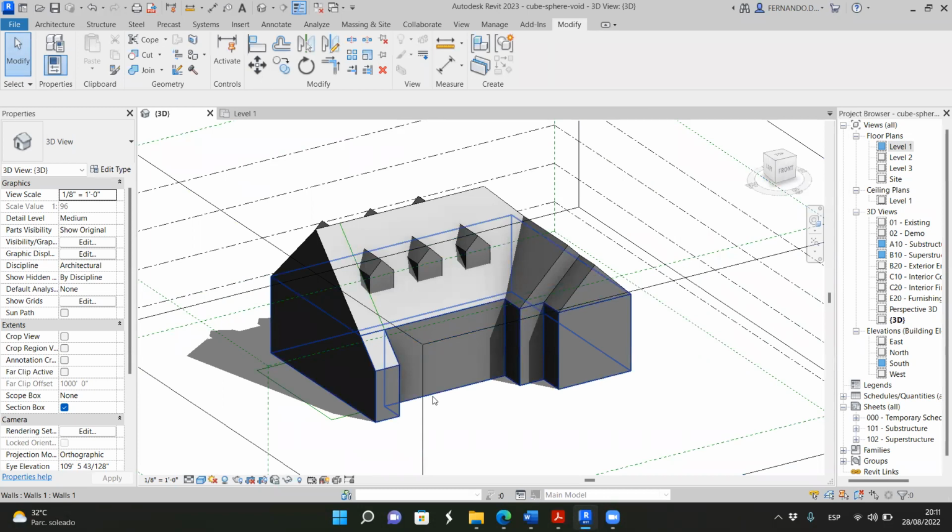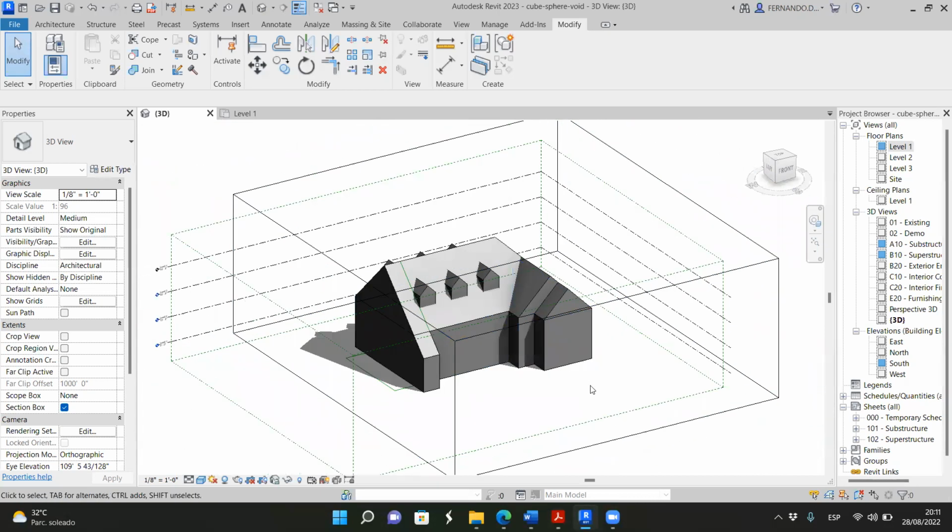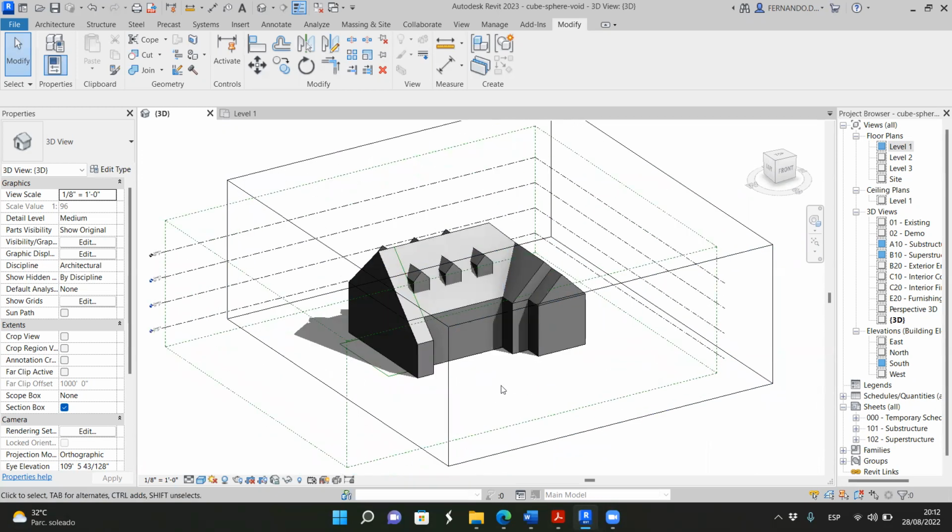So now we have shadows and we have shade here, and that's important because when we cast shadow here, the building is not floating. Okay, so if we don't cast shadows, it looks like the building is floating. But if we do, we convey the idea that we have a floor. Okay. So if we want to create a nicer screenshot from this, we can use the hide options.